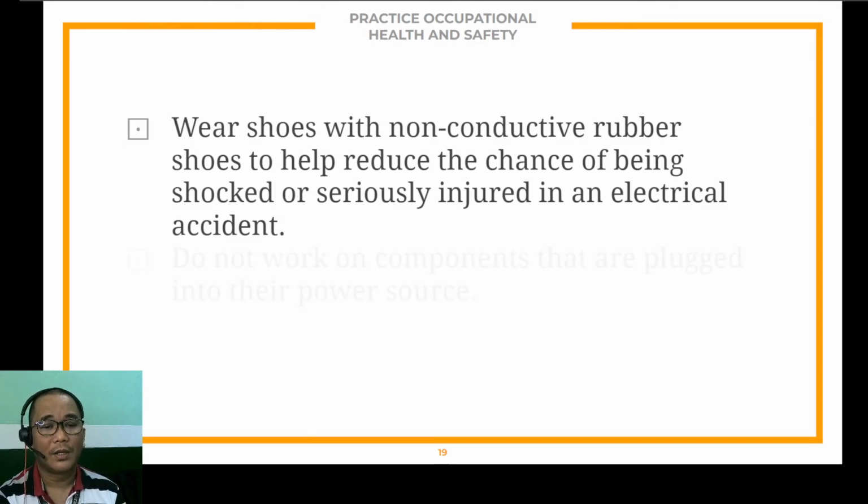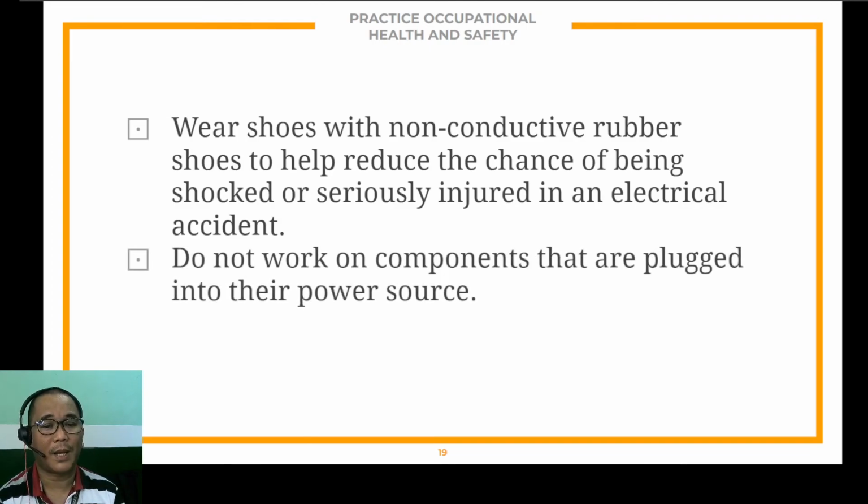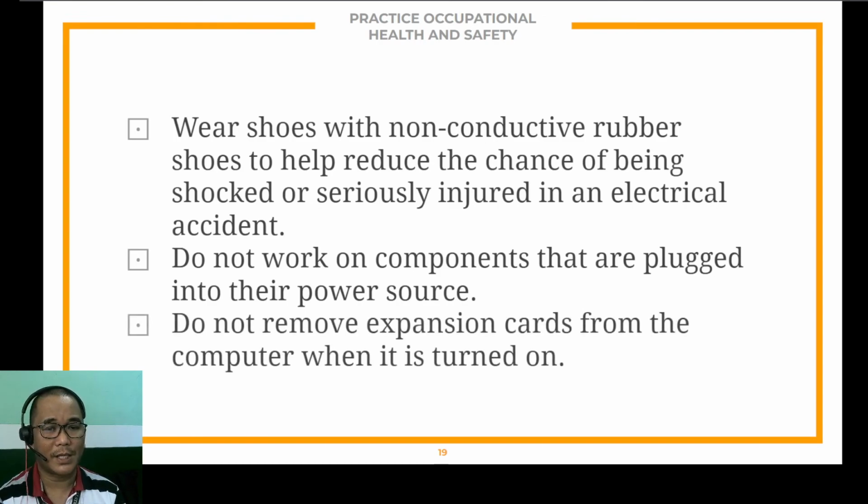The next one, do not work on components that are plugged into their power source. As I said before, you need to turn off the computers first before working on them to avoid an electrical accident and also to avoid damage to the components. Then the next one, do not remove an expansion card from the computer when it is turned on or it will damage your expansion cards.